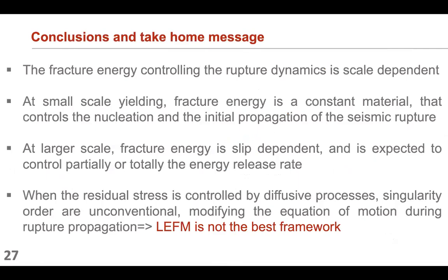So the fracture energy controlling the rupture dynamics is, as I show you, scale dependent, even at the scale of experiments. So at small scale yielding, fracture energy looks to be a constant material parameter that controls the nucleation and the initial propagation of the seismic rupture. But at larger scale, the fracture energy becomes a slip-dependent parameter and is expected to control partially or totally the energy release rate and the dynamics of the rupture if you have rupture lengths that allow for the far field weakening to catch up the initial rupture tip that propagates along the fault.